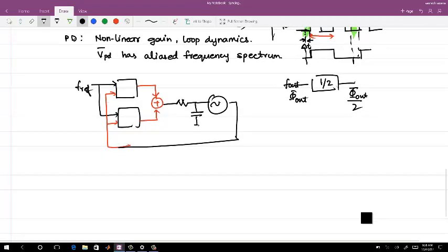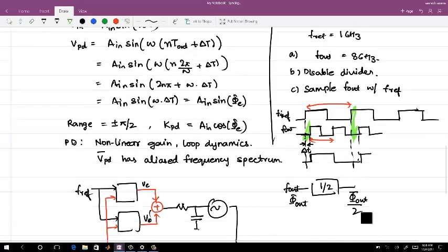First thing is, if you are using the same kind of phase error detector, whether it's a multiplier or this subsample one, their characteristics are the same. So whatever V error you get here or here will be the same. You will not be able to distinguish between the two; it will be just some offset from one or the other, because the input-output characteristics are the same, sinusoidal.